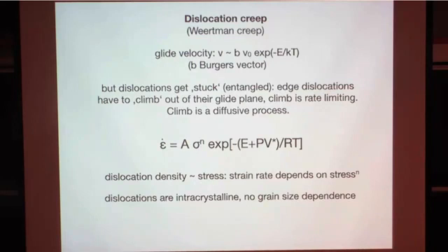It's grain size independent, but at the same time, the stress that you impose actually modifies the dislocation density. So there's a feedback between stress and dislocation density. The point defects were not affected by the stress. They just move. But the applied differential stress does not generate the point defects. There is a thermodynamic reason for that.